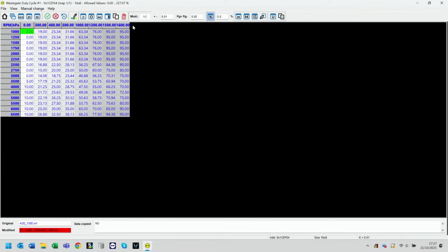With these on a good stage 2 and looking at probably a high flow pump, we can quite happily run up to 1.6 bar on these engines without any internal modifications or forging. But at that point, you are really on the limit of what the standard turbo will do. So even with stage 2 bolt-ons, still only about 1.4 to 1.5 bar as an absolute maximum.